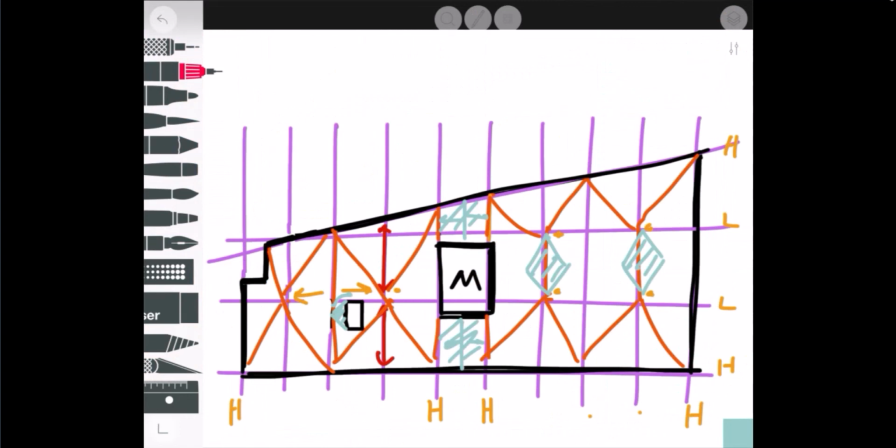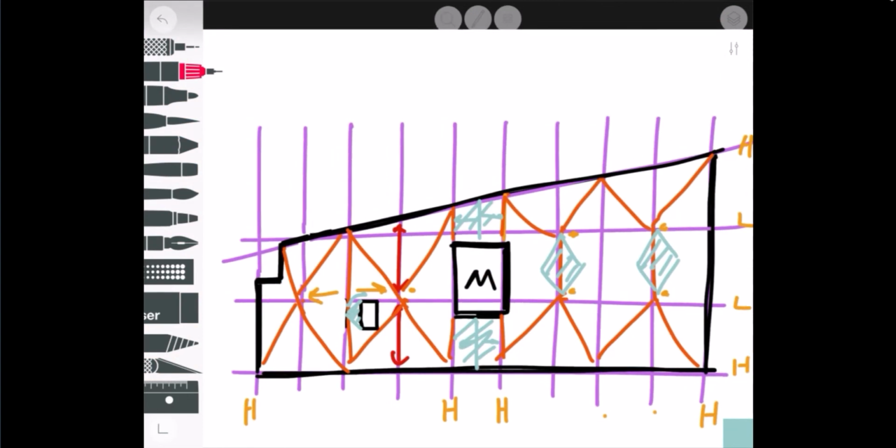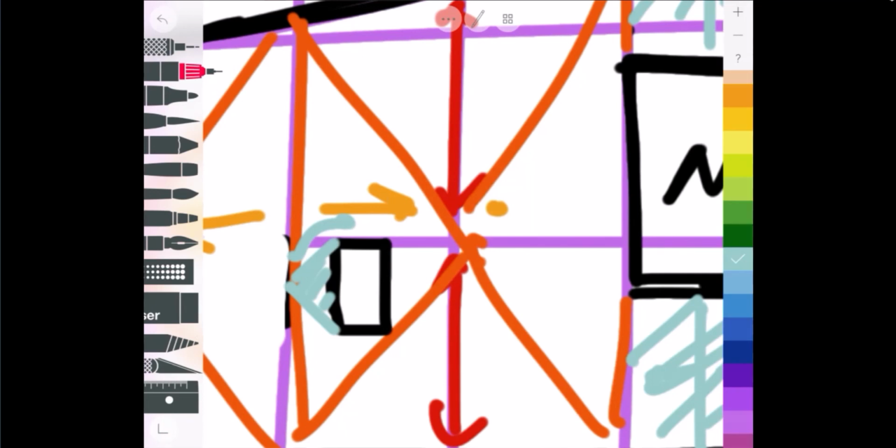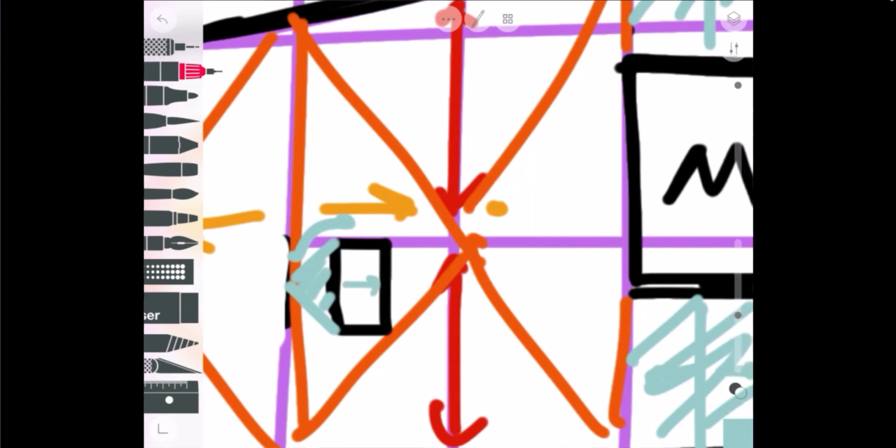So you do that like at an elevator overrun, and not to mention the elevator overrun itself would want to slope, not be flat. So you want to slope it somewhere. So it makes sense to slope it off this side because once the water gets down, it's going to make its way that way. So, depending on whether there's a parapet in there or you just, it depends. You could just run it off the edge depending how high that is.